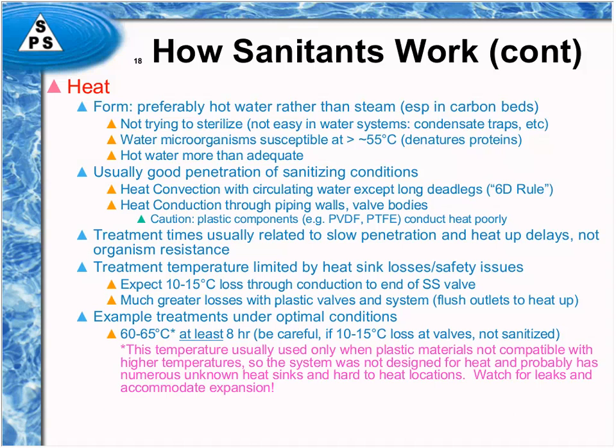Now, frankly, whenever you use this kind of condition, it's because the system was never designed to be heated to begin with. You're using it as a last-ditch effort because everything else has failed. And whenever you use hot water in a system that was never designed for hot water, you have to be careful, because the system may develop leaks. The piping may sag, because usually these are plastic systems. So you have to really be careful when you use this kind of sanitizing approach.